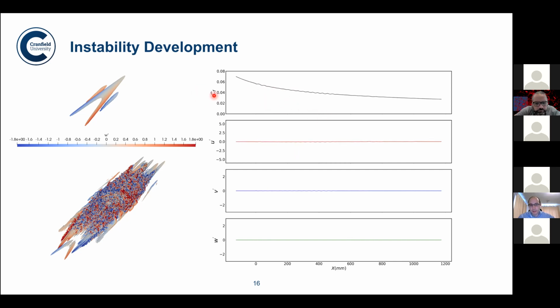We're seeing the skin friction at the wall, and the unsteady velocity components for the streamwise, normal, and spanwise components. And we can see the linear regime developing, and slightly bigger structures starting to appear that will develop further and then lead to the sort of burst that we can expect with the appearance of a turbulent spot.